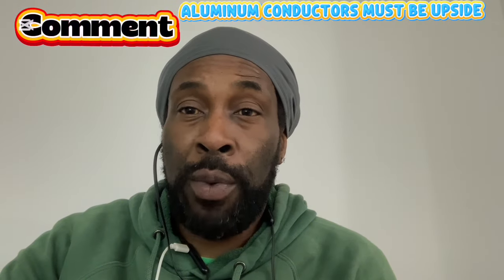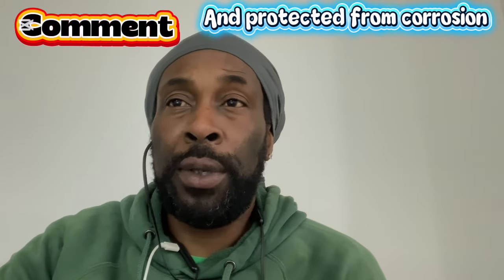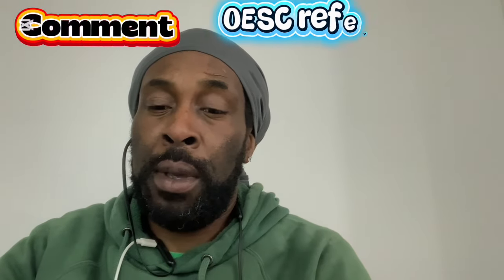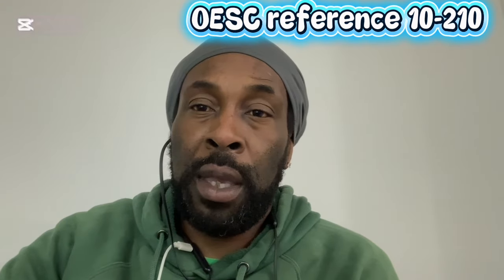Aluminum conductors must be upsized and protected from corrosion. OESC reference Rule 10-210 plus Table 16.